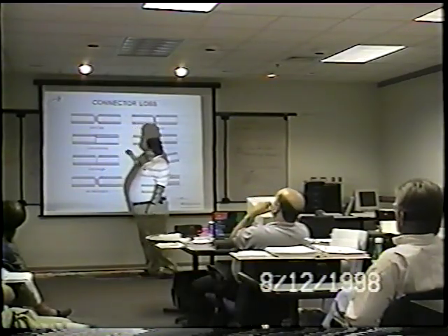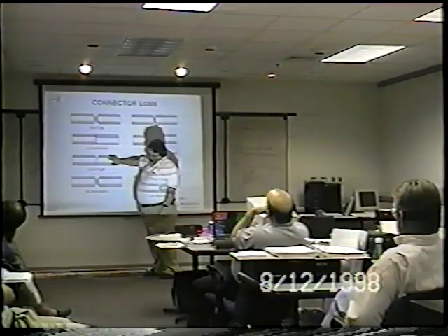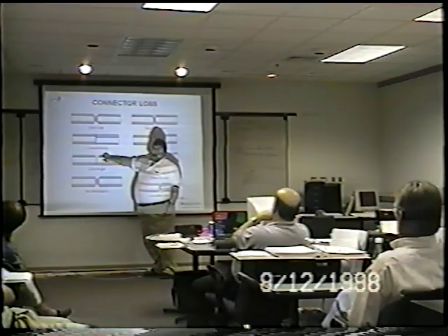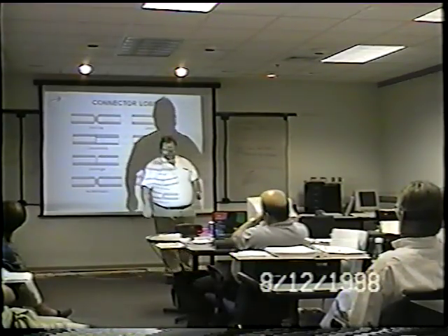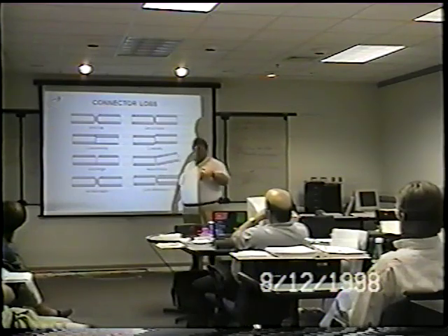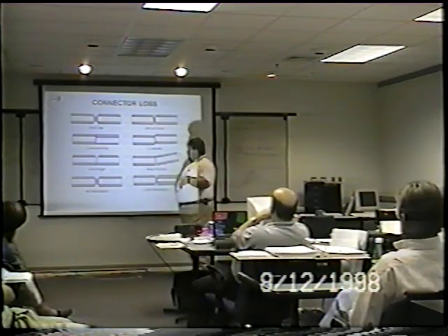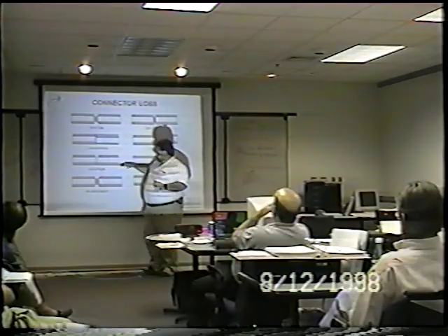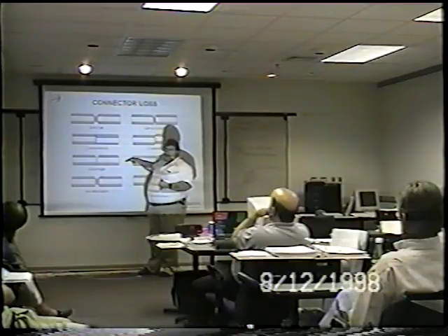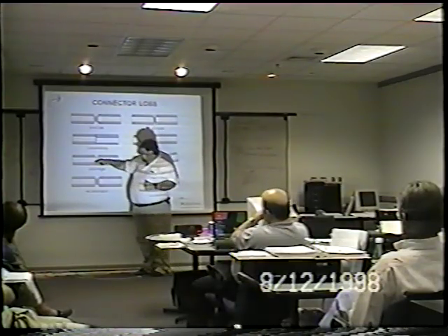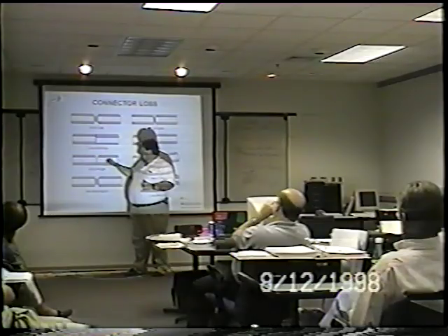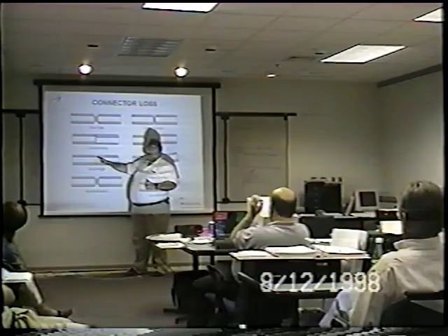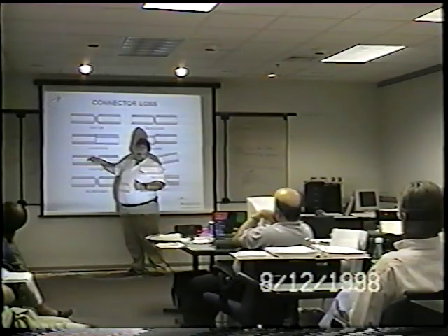The only exception to loss is that in certain cases there will be on-purpose terminations of this style, where you have an end angle put on the connector itself. Most of the 1550 optics that come from MRV will have an intentional offset of the polishing, because if this is the emitter side at 1550, any light coming back in, any reflections off the connector tip itself, the reflective component goes off in this direction and not back down the fiber.